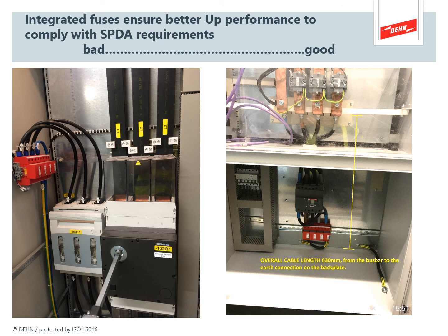So that cabinet and several others like it were rejected on site, and the panel builder had to go away and re-engineer this. So we can see now the SPD is in a different location. It's in another separate compartment with, this time, not fusing but a molded case breaker rated at 25 kA. So that's absolutely fine.